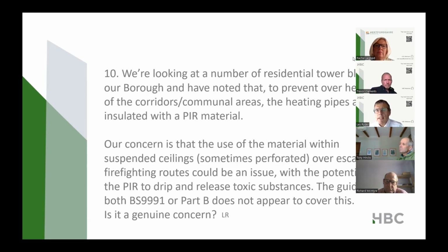My feeling is that the common areas are at the very least tenable, what we try and maintain is a tenable condition. If it's a staircase, a firefighting staircase or a normal staircase, that's sterile. We don't want any smoke or anything in that, and any smoke that does get in there, we try and get rid of it with the AOV. The corridors are considered as what's called tenable, i.e. what we try and do with the corridors is we try and keep them under a certain temperature. We try and keep any smoke that does get into there at high level, and we try and ventilate it out. And any radiant heat points we try and keep to an absolute minimum. So it's a tenable area, and the heat that's necessary to combust PIR under normal circumstances won't exist.